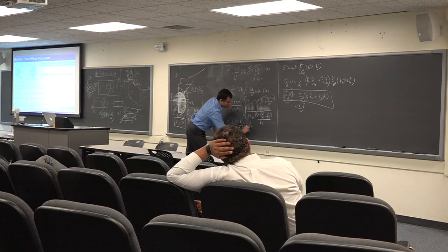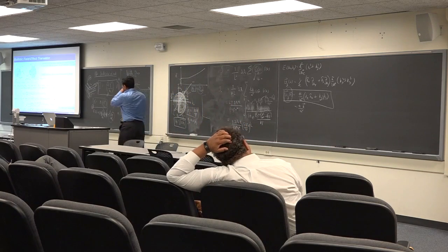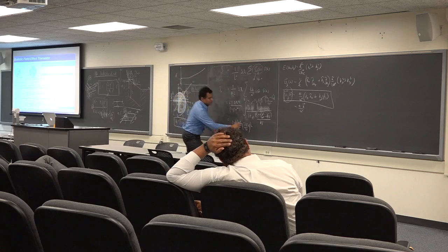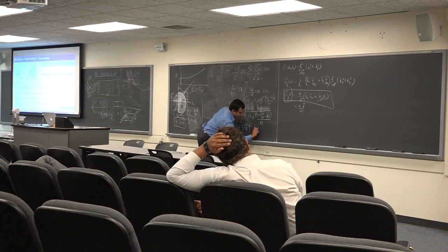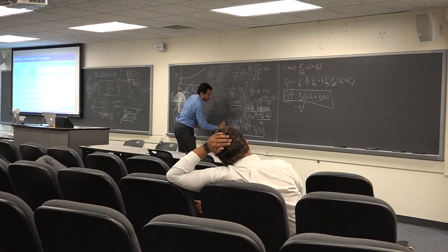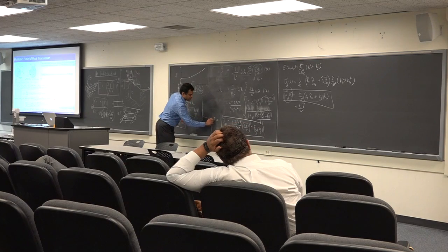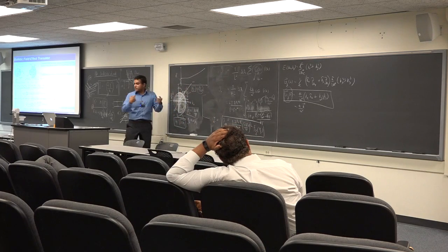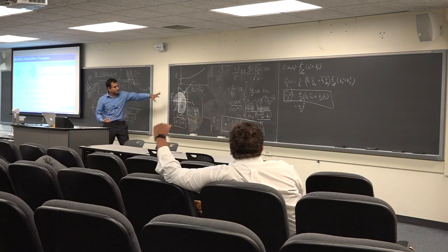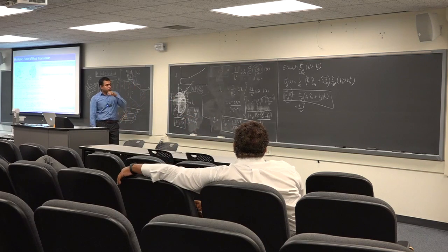All right, so that's how it looks, times the Fermi-Dirac integral of half order. All right, so that's the current going to the right, just the current going to the right, and that's obviously also equal to the magnitude of the current going to the left. It's no different, right? So they're exactly equal when you have no voltage applied on it. Is that clear?